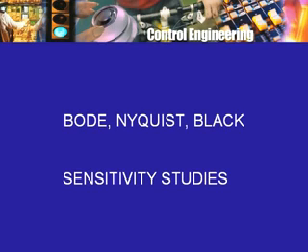And in fact, Bode introduced a particular measure of sensitivity. How sensitive are some of the things, for example, the steady value of the speed, to variations in load torque, variations in applied voltage, error made regarding the value of Kb or Kt, or change in the field current, things of this kind. Sensitivity coefficients of various kinds can be calculated,